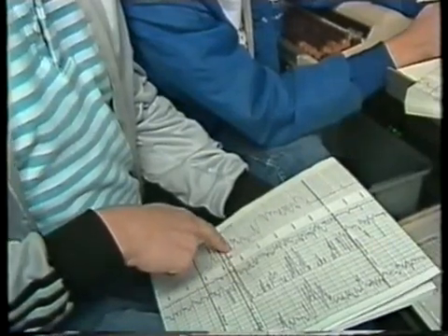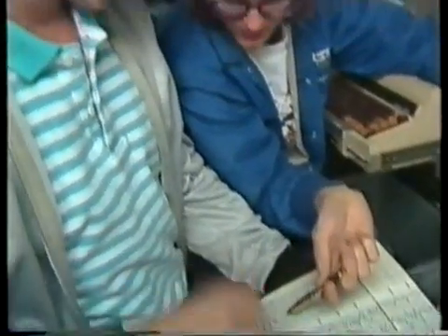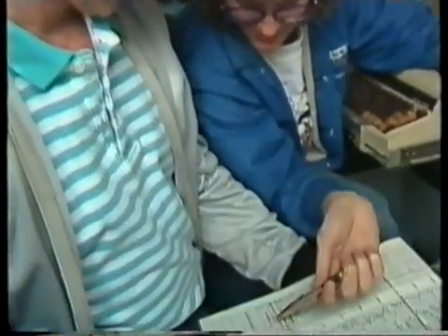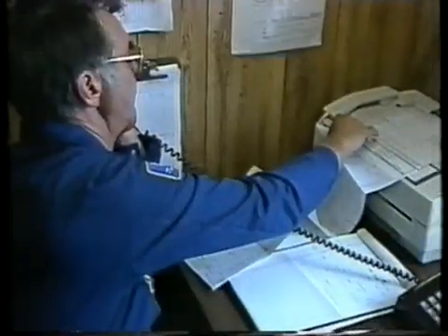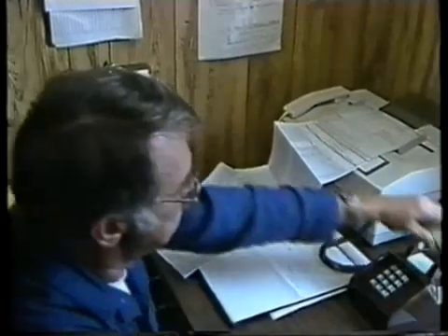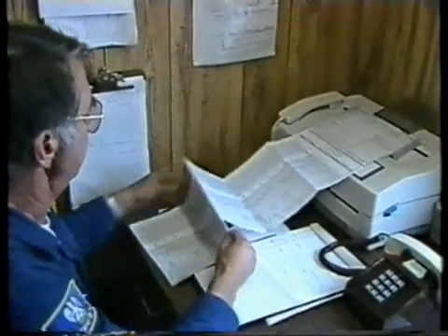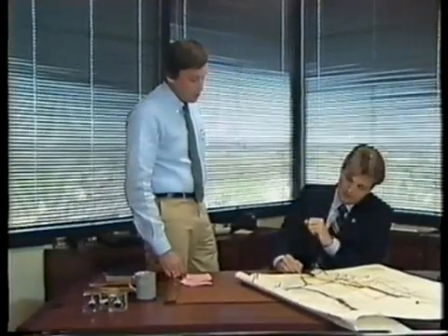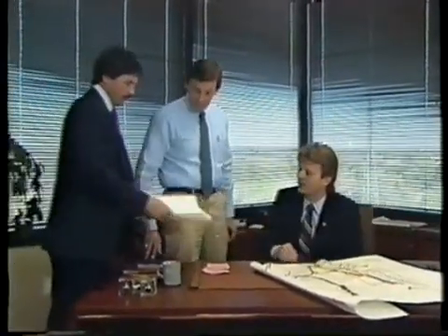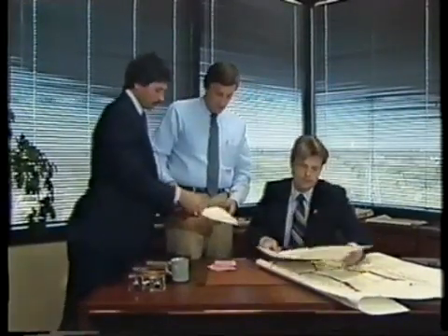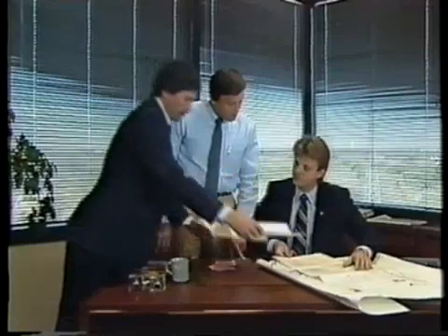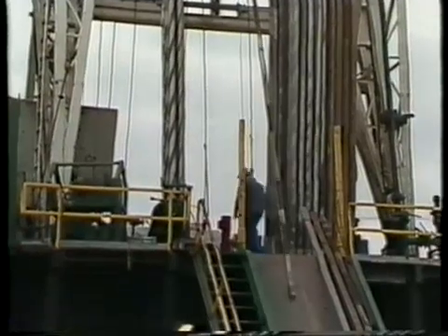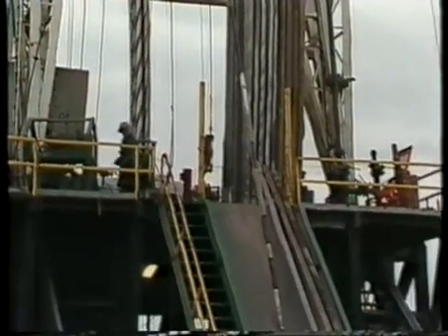Therefore, it is essential that the oil company representative and the logging engineer communicate effectively with each other throughout the survey, and that accuracy and details are obtained on the initial field prints. It is possible to transmit logging data via satellite or facsimile machine directly to the oil company's offices. This can be done after the logging run is complete and permits staff geologists and engineers in their offices to approve a run, participate in the selection of sidewall coring and fluid sampling depths, and modify subsequent runs of a logging survey.